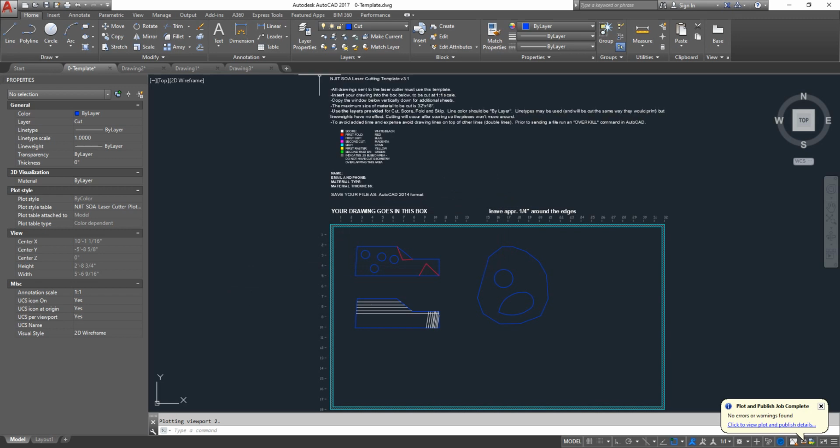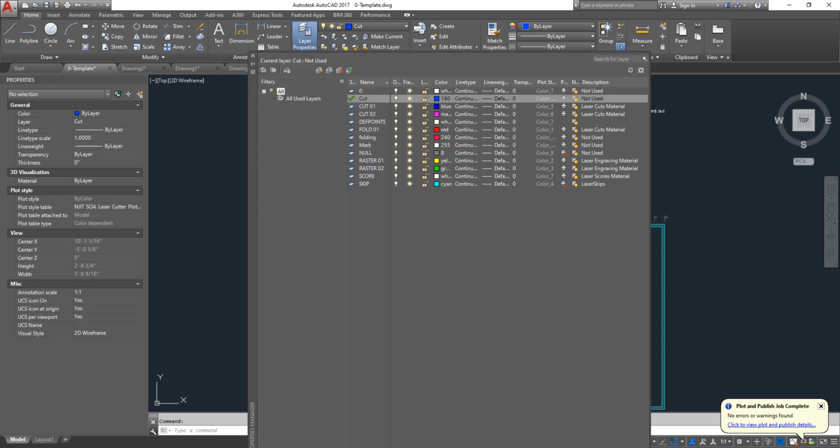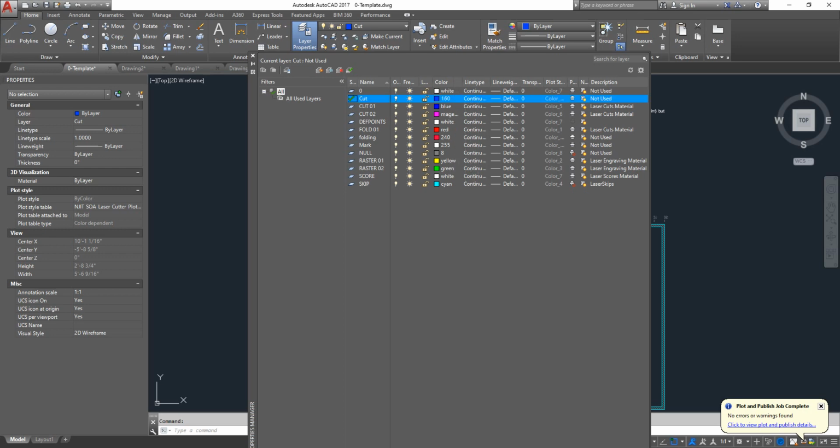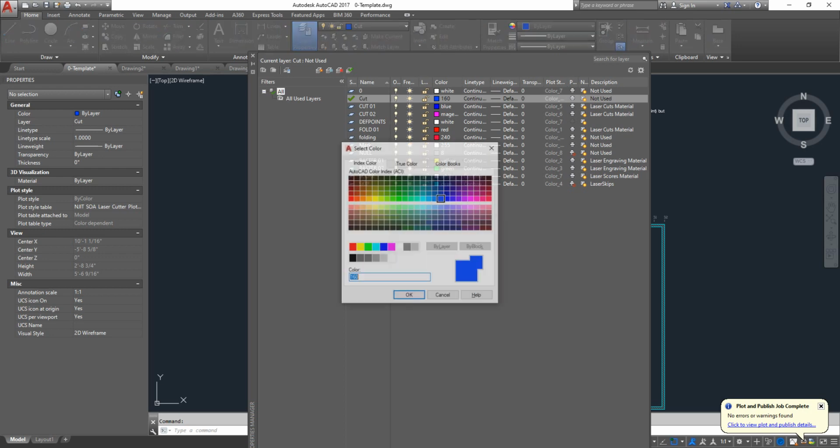And why is that? Well, if we look at the actual layer properties, this is very common, especially from Rhino. It comes in, and what you told Rhino was blue. Rhino defaulted blue as color 160, which is blue, but it's not machine blue, if you understand. AutoCAD actually has a long history with getting Microsoft colors locked in. So if we go to this color palette, you'll see down here there's the basic colors. So when it says you need blue, that's blue, versus the 160 or 180 that it was previously.